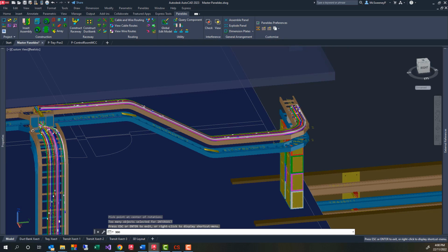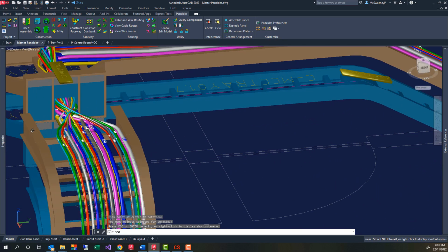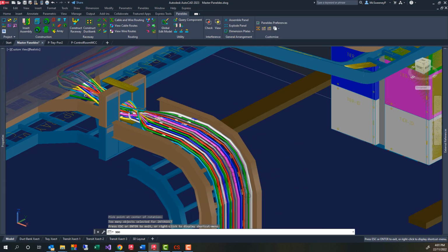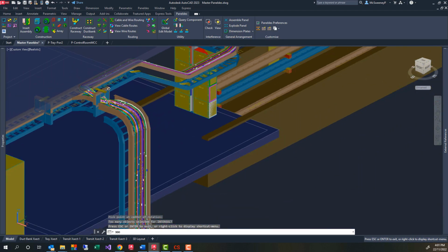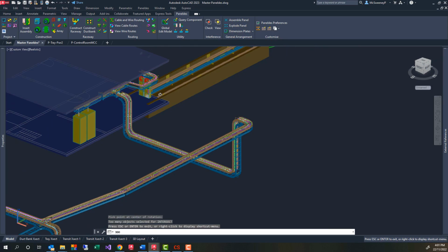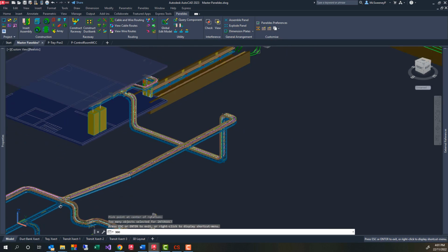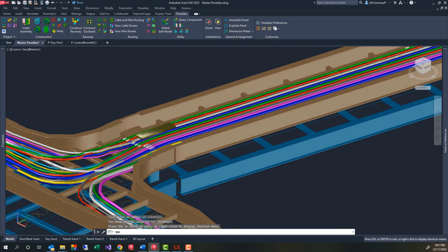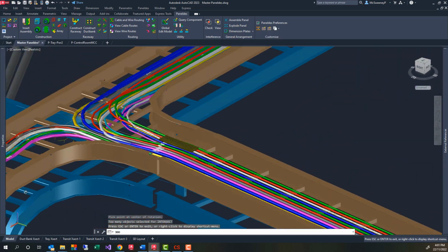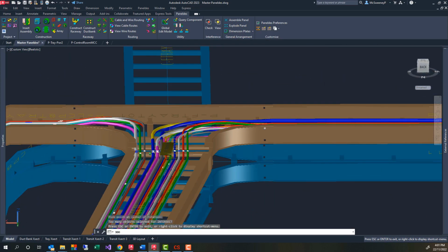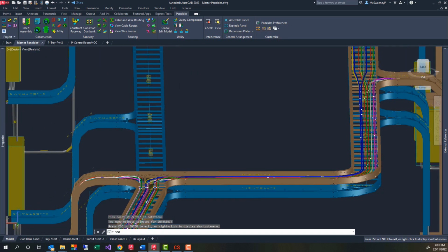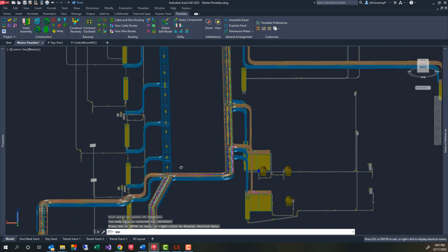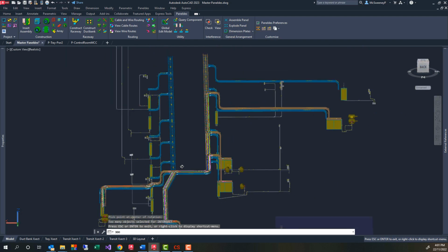The cables all share the same frame in the transit, which is exiting the control and power building. The tray out to the plant looks tidy and the T-junction in the plant looks good. The cables all appear to be tracking nicely to their in-plant destinations. Note, trays can be physically split with dividers if they are filled with mixed power cables. Paneldes tracks and manages these splits to ensure the cable cross-sections are accurate.